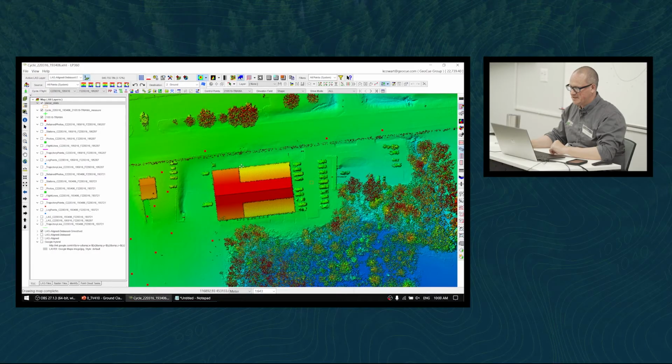And it's worth noting that this mostly compresses hard surfaces. Complex features like trees and power lines, it's not going to affect those much. It may compress grass some. Yeah, so this is what we're looking at. And this is the data set that we're going to move forward with for doing ground classification now.